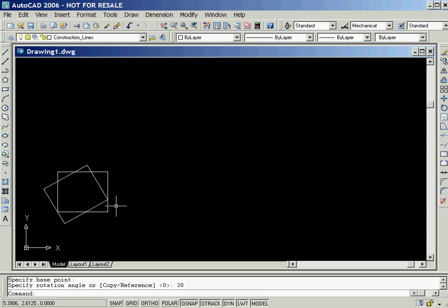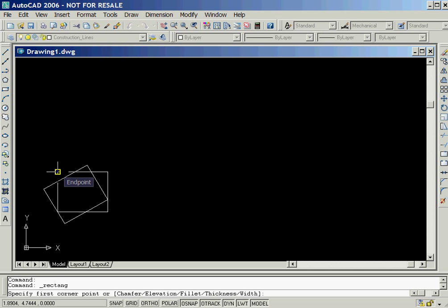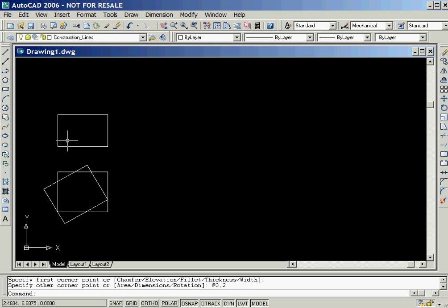We'll now begin to draw the top view of the V-block. After selecting the rectangle icon, we'll now locate the crosshairs over the corner of the front view in order to activate the Object Track Alignment feature. Now we'll position the crosshairs about 1.5 inches above the corner and then left-click the mouse, followed by keying in at 3,2 in order to define the other corner of the rectangle.